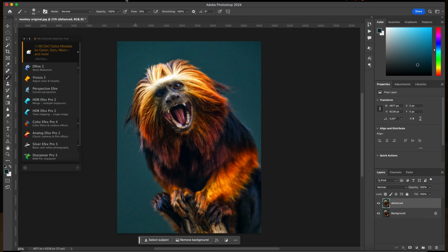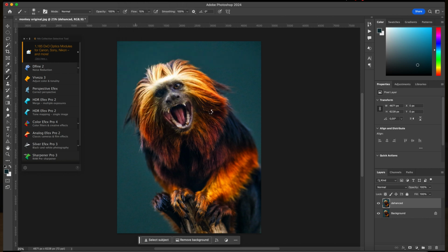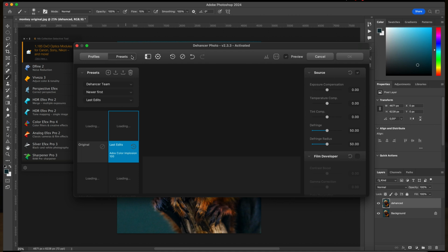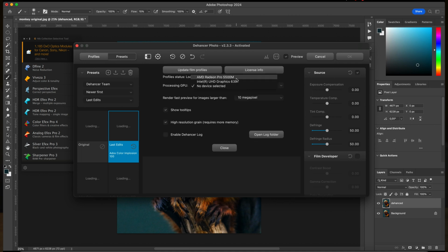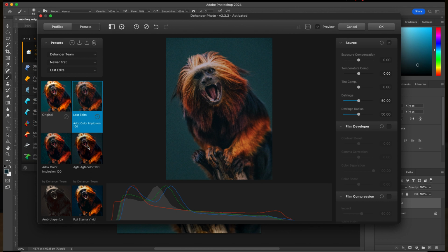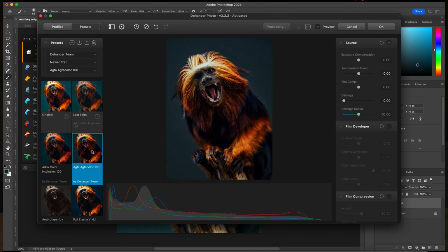First of all, by default, when you first launch the plugin, as I mentioned before, it does not choose the best GPU that you have on your computer. You need to go to the settings and set it yourself. So after you choose the GPU that you want to use, if you just wait there, it will take ages before the plugin actually shows any preview. That's why I say that it helps to close the plugin and then relaunch it. It would be nice if we did not need to close and relaunch the plugin.